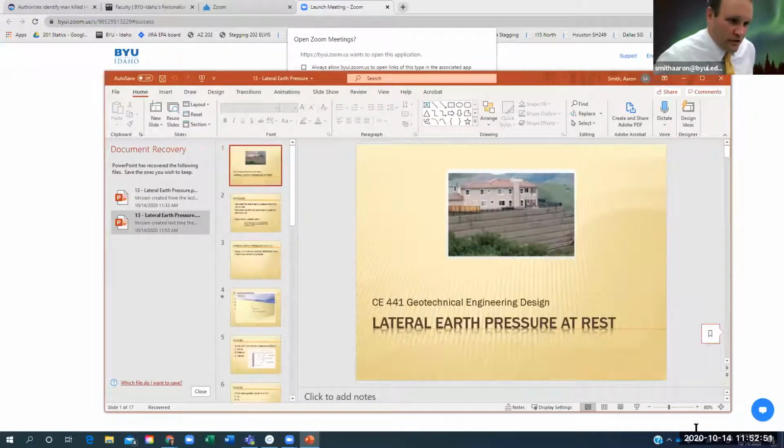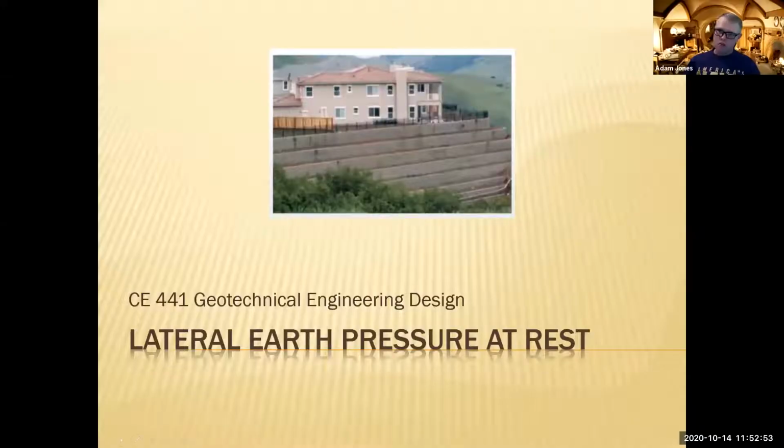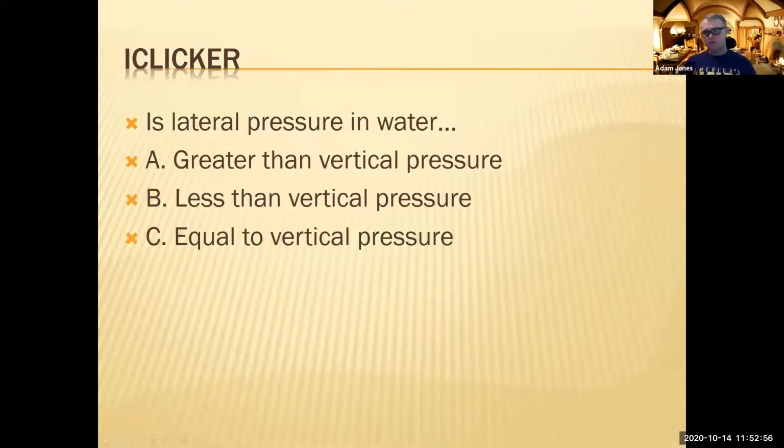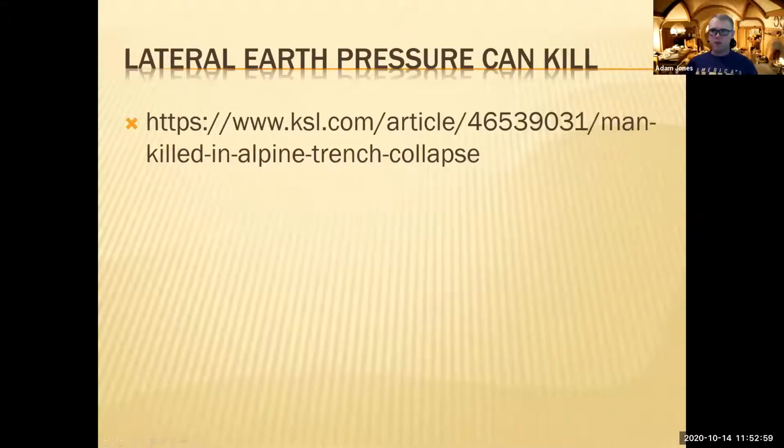Okay, tell me about where you were inspecting. So the first project, they were putting in a new sewer line. When you're laying pipe, people are in the trench all the time, and they didn't want to have to deal with a trench box the whole time. So they subbed out the street down 2 feet because they were going to put in new sub base for the road, and then they only had to go down another 4 feet. But when they excavated, they V'd the slopes way back. So they were at 4 feet most of the time, which is OSHA approved, but having them V it at the same time gave us a much lower chance of this happening.